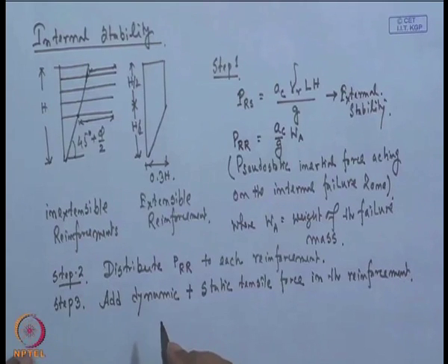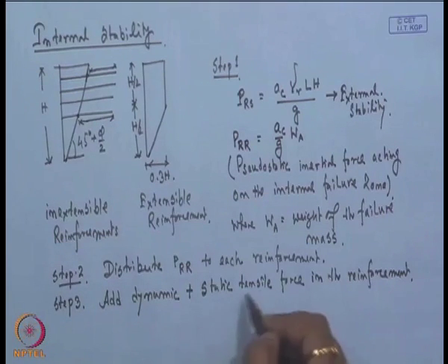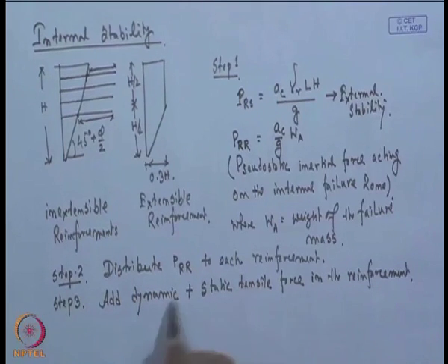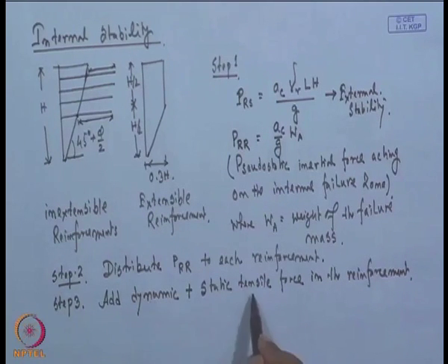Previously we considered the static tensile force, and based on the tension force developed in the reinforcement, we designed our spacing and then the length. Now, due to this dynamic force, there will be an additional tensile force that develops within the reinforcement. So, we have to add this additional tensile force to the static tensile force in the reinforcement.